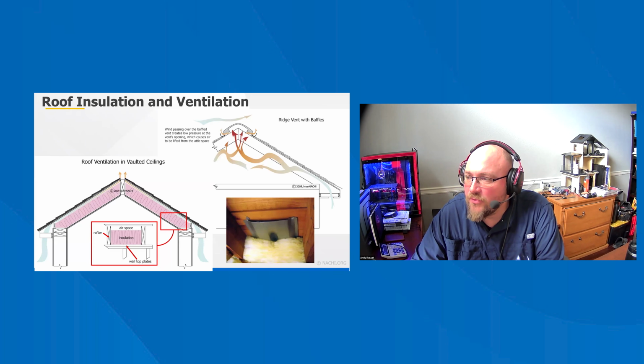In colder climates, roof ventilation serves to remove humidity and condensation from the roof attic space and helps to prevent chronic formation of ice dams at the eaves. Tile, concrete, and metal roofing materials are not similarly affected. It is possible to have an unvented attic space, but such a choice may require designing the attic roof space as a conditioned space, similar to that required when creating a habitable space in an attic. There are several sources that provide detailed information for designing an unvented attic. Traditional attic ventilation remains a cost-effective, though imperfect solution for moisture control.